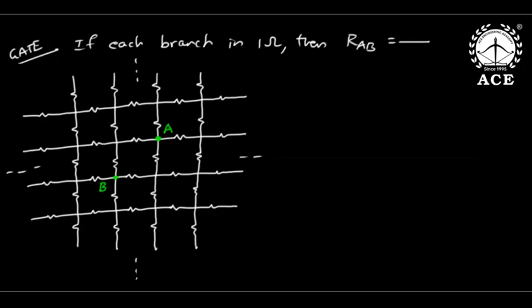Everyone see, now here we cannot apply the ladder trick, because in a ladder at least it was going in one direction, so that infinity plus and minus one infinity we can do. But here, with respect to this AB, all four directions are a symmetrical pattern and cannot be distinguished. In a ladder, at least it is going in one side, so I can take that infinity plus and minus one infinity by identifying a periodic segment. But here in all four directions the periodic segment cannot be distinguished.